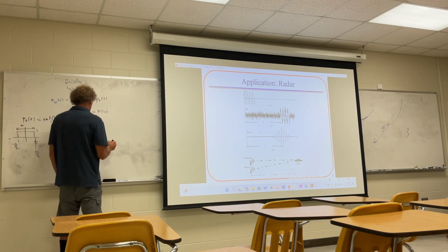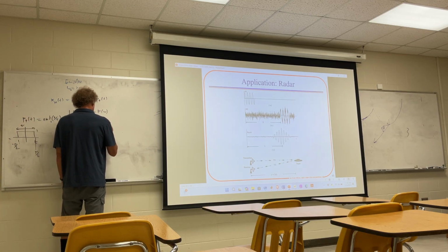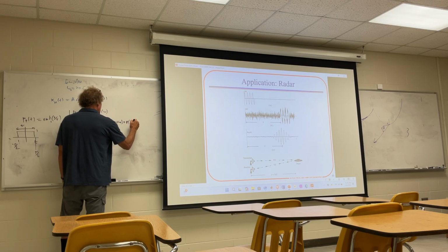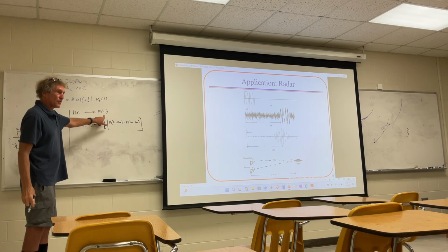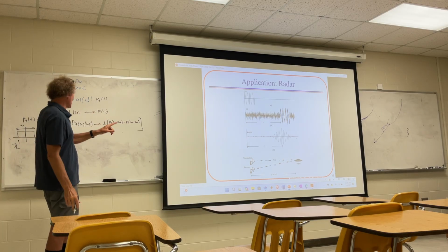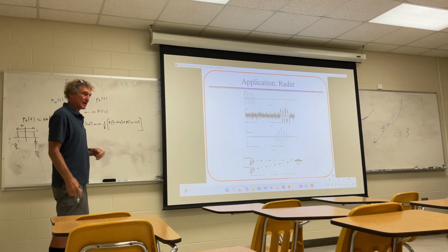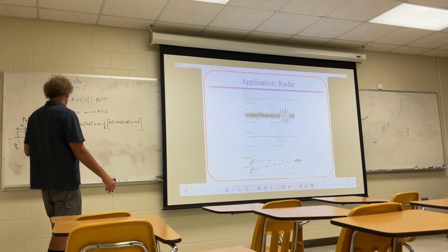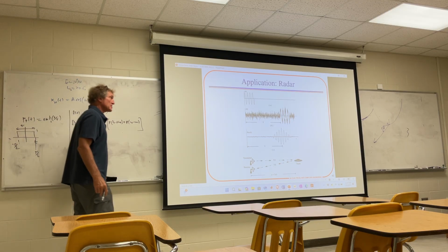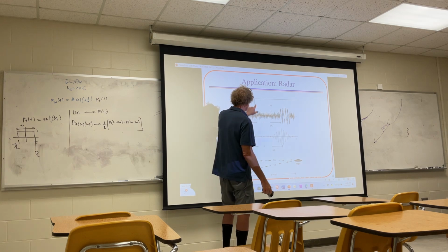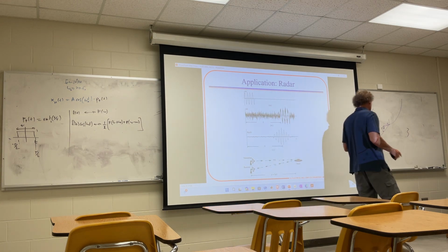This actually has a transform of 1/2. I think you know this though. And now it's going to be times f of omega plus omega naught plus f of omega minus omega naught. Now the reason I'm saying it that way is, if I know this transform, then I simply take that transform, whatever it is, and I push it and center it at minus omega naught and plus omega naught. Everybody with me? I'm going to do this example, make sure it's clear to everybody. Back to this thing so you understand why you have to have a lot of cycles to transmit this. And I'm doing it over here because I want to leave that up.